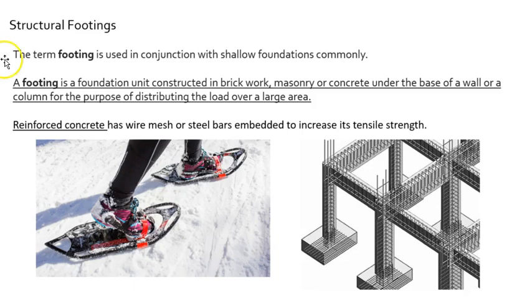Structural footings are a component that are typically used with shallow foundations. They're constructed out of brick, masonry, or concrete. They live under the base of a wall or a column, and their purpose is to distribute all of the building loads down into the earth. So down here is where we see the foundations, the footings. The footing is one component in a foundation.